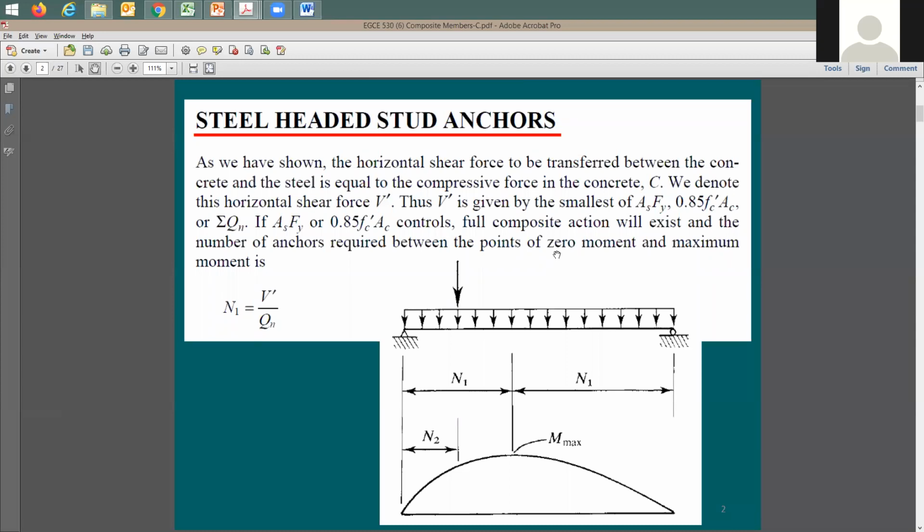Okay. So we're going to figure out how much is the dead load deflection, and say that camber is going to be almost the same, or maybe 90% of the dead load deflection. Some people would say I'd like to keep it as 75% of deflection. So we're going to get there. When we get there, I'm going to explain it. All right. So we're moving here in steps. So now I need to figure out number of Nelson studs.